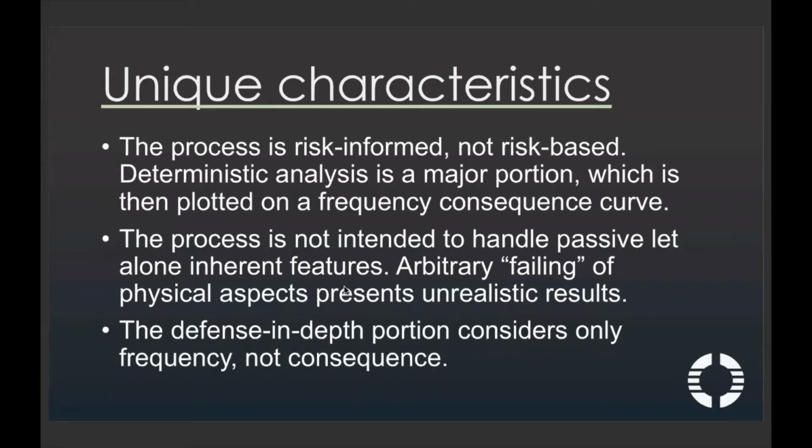You also do deterministic failures of the system, and then the process part of it is where you take those results and utilize tables and so forth to determine how you use those results and actually categorize your components. That was the part we took issue with: categorizing components by considering how their failure affects frequency alone, without considering the holistic consequence, the actual risk, which is the frequency times the consequence. And I think part of the reason the methodology came about like that is because many of the developers had a background in light water reactors, and so consequence was kind of assumed.